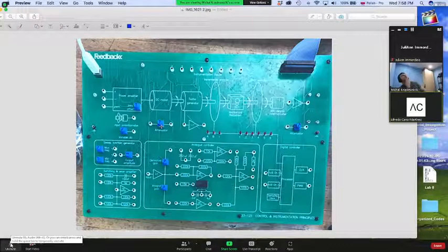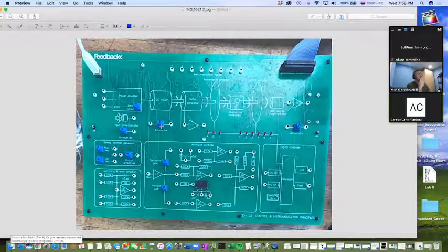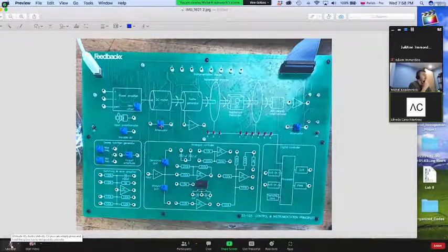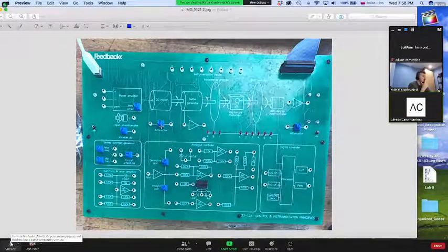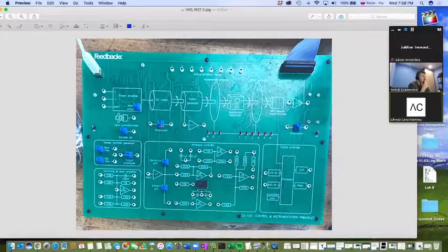In order to dynamically increase the gain in the system, you cannot just be switching around the resistors in the error amplifier. You use this knob to increase the value of the proportional signal. In most cases, this attenuator works as your gain.